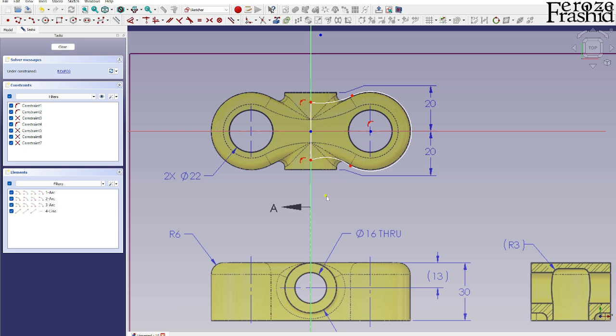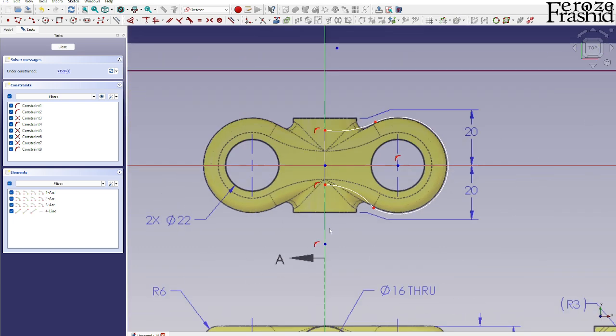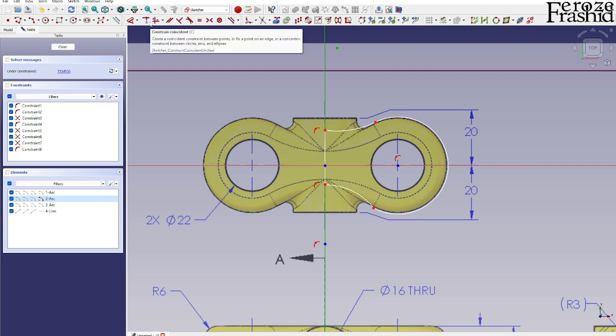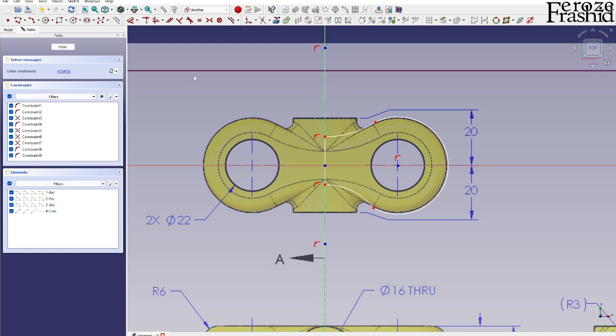All right, so first of all, I want to take this point on this line that way. That places it on the horizontal tangential side. So I'm taking this dot and selecting the axis and hitting C on the keyboard. C is the new coincident constraint, so I can press it here or just hit key C from the keyboard. That does the trick. And for tangency, we want to apply some tangency here, so that is the command T.